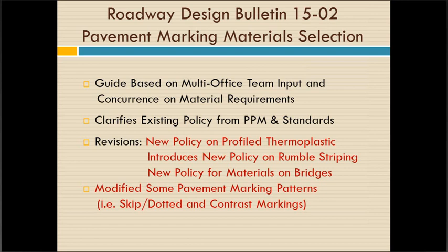We've modified some pavement marking patterns. It really does not affect too much except for one item: skip and dotted. We have had a discussion over a year now on the definitions that are in the MUTCD in relationship to the patterns that we use. So we have gone through skip and dotted and clarified what is a dotted line and what's a skip line. We've also changed our policy on contrast markings. So if you've got contrast markings, you'll see the changes on contrast markings.